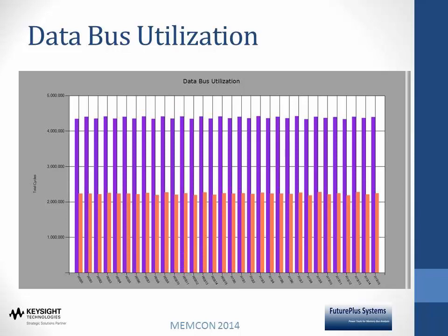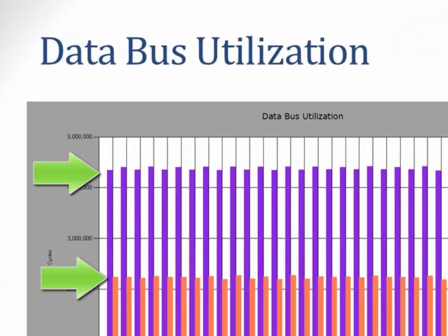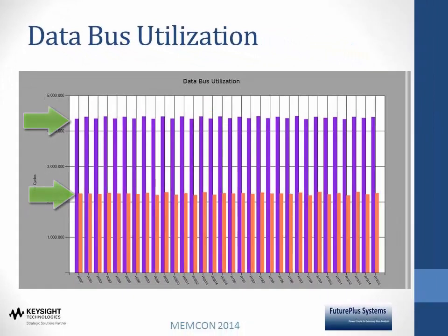This is the whole reason for memory to exist, to store and transfer read and write data. Since the command bus dictates what is seen on the data bus, the distribution of commands will look similar. We can see that the reads are approximately 2x the writes, and the data is evenly distributed across all banks and ranks. This view is useful to see if your system is write optimized, if that's what you are aiming for. Also, in a chip kill or page retirement scenario, you could quickly see how the traffic is reallocated.